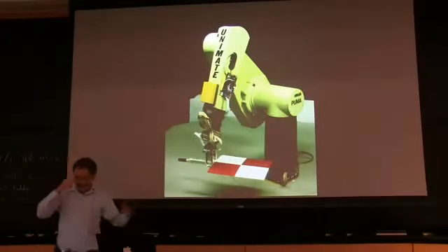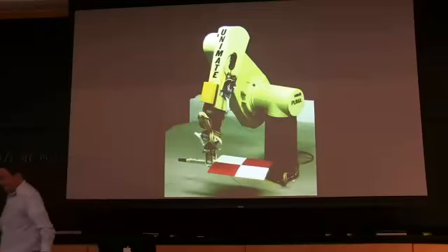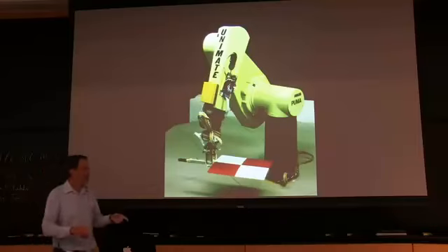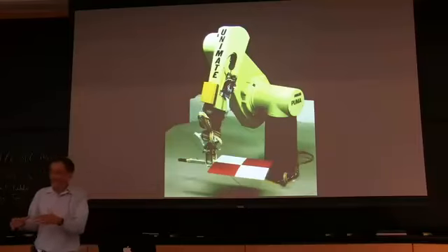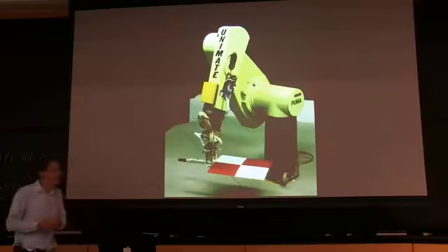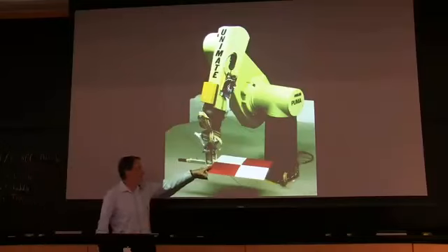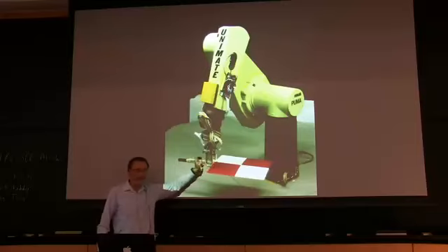And I show this because another calibration I left out was what I previously mentioned, the relationship between the robot coordinate system and the vision system coordinate system. One way of dealing with that is to have the robot carry around something that's easy to see and accurately locatable.